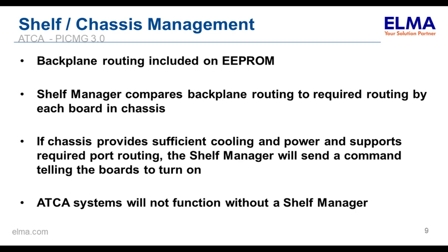Furthermore, the chassis manager will read the EEPROM and gather the power information, power per slot, and total power per chassis. So the chassis manager then will compare the chassis routing information, the cooling information, and the power information to what the boards need and decide whether the boards can start up or not. So a standard ATCA system will not function without a chassis manager or shelf manager.